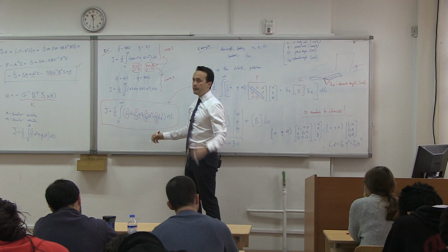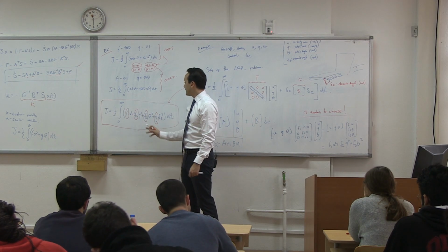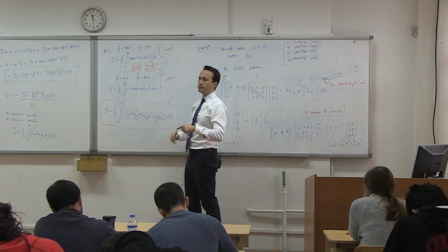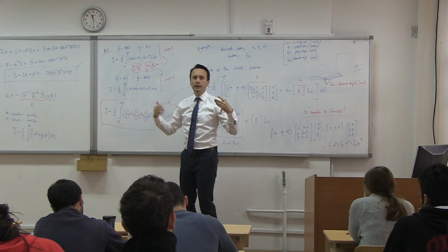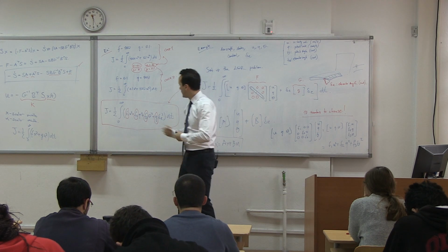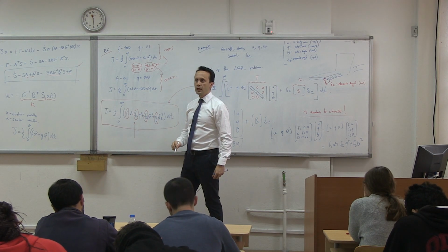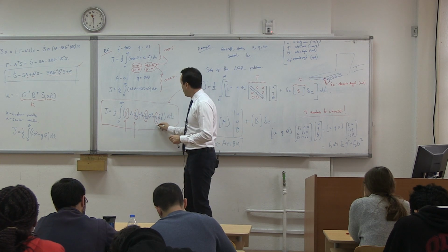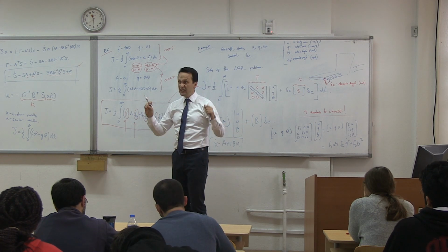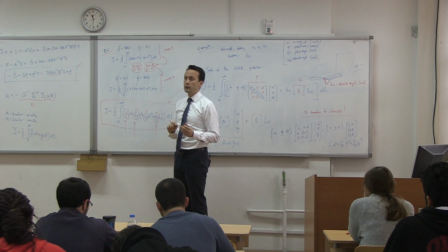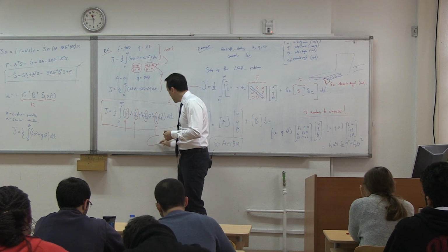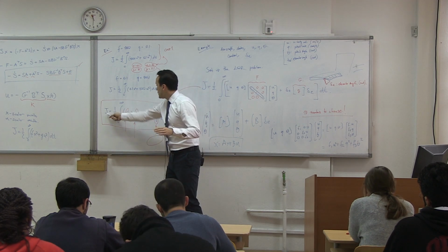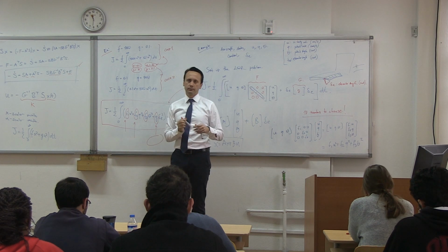So just like this argument, I'm going to ask you, which one is more important to you? Del E, Q, or U? Which one do you want to move the least? I'm just making this up. You might want to say, I want to move Q the least. I don't want Q to move too much. Okay? Make this number large. And you might say, U, the velocity, I don't care, so make it small. You might say the control movement, I want the control movement to be as little as possible. I don't want the control to move too much. So then make this a very large number, and del E will not move too much. Okay? At the end, the optimization problem will add everything, and it will minimize J.